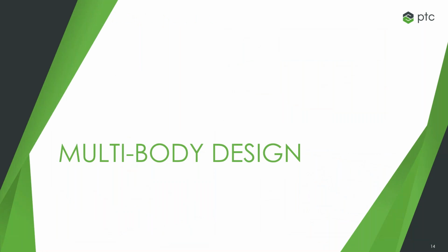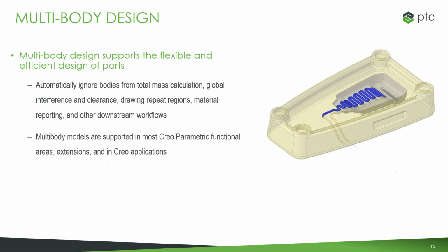I will go through and show a demonstration of how we work with Creo Simulation Live flow analysis towards the end. But one of the other big enhancements that we've had in Creo is the ability to work with multi-body design. It's offering a new way to design in Creo. If you haven't worked with multi-body design, it's a methodology that allows you to be flexible in the way that you design your parts and the rest of your model, where these bodies, each of them can be handled differently. You can apply different materials, include or exclude them in your mass calculations, define how your global interferences or clearances work, and many other options around this.